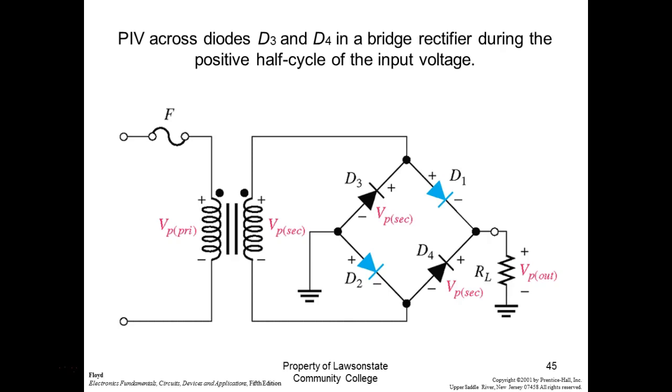Well, I can't. If I was going to measure across this with my oscilloscope, then I would have to hook up a ground right here. I can't hook up a ground right there because I've already established the ground over here. You understand? So once you hook up an oscilloscope, then basically that's it.